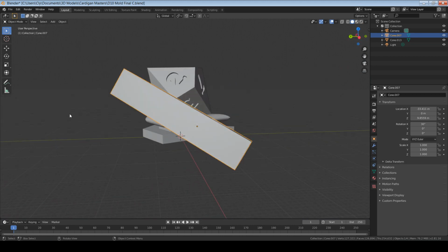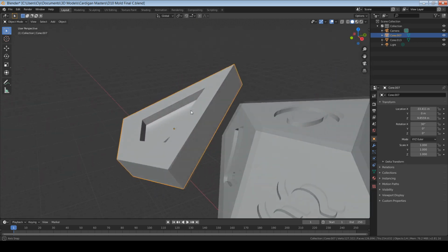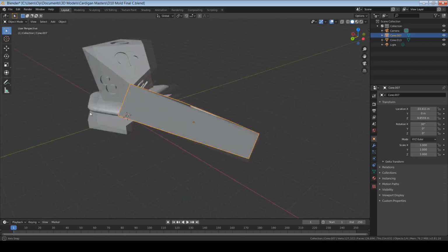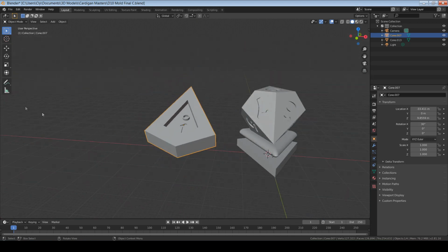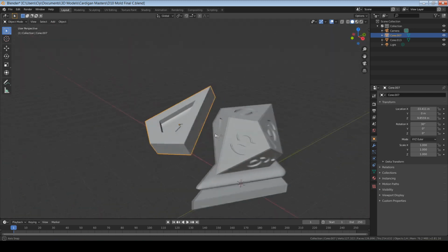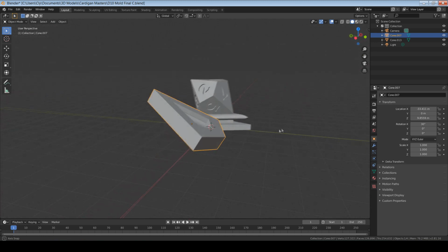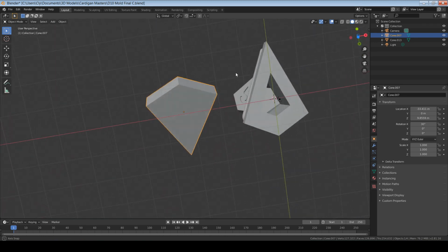This means that you not only don't need to remove the supports from your dice, which I should add sometimes splinter off and leave divots behind, but you also don't need to sand off the support remnants either from the master die or from the dice cast from a mold made from an unsanded master. Also, I have things set up so that you can remove the silicone from the master die without having to cut it. It just peels right off. So now not only is making molds faster, but you don't have to worry about potentially ruining your master dice every time you make a mold.